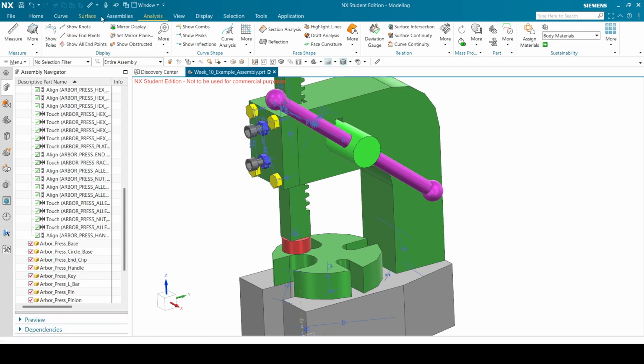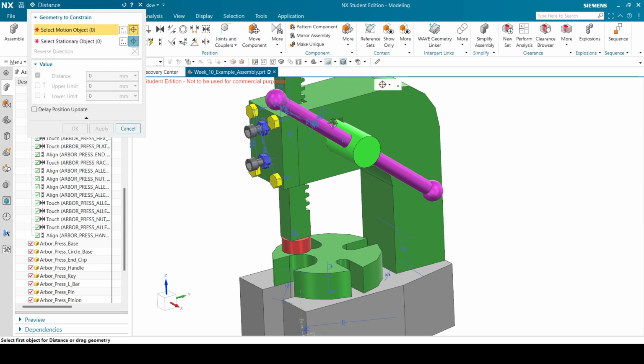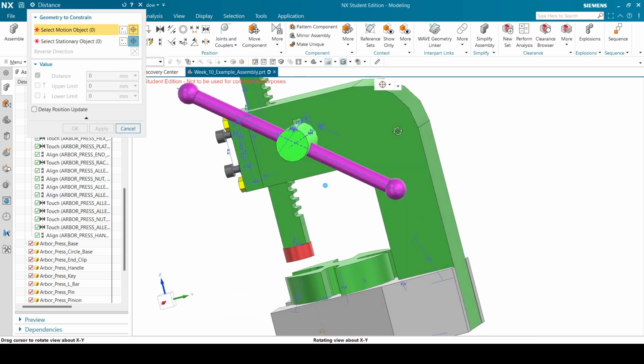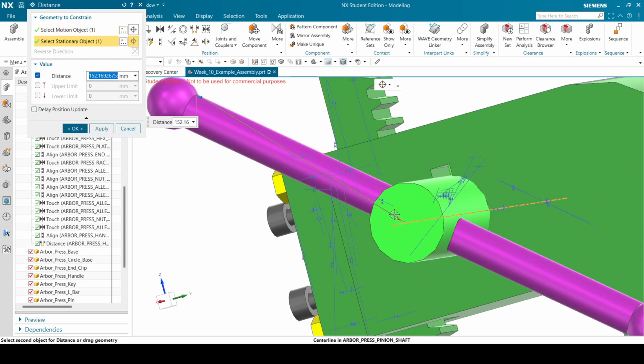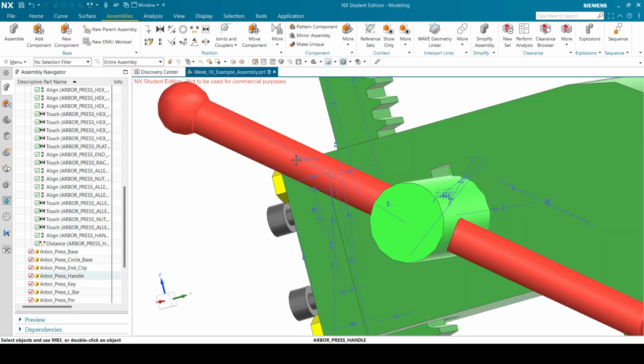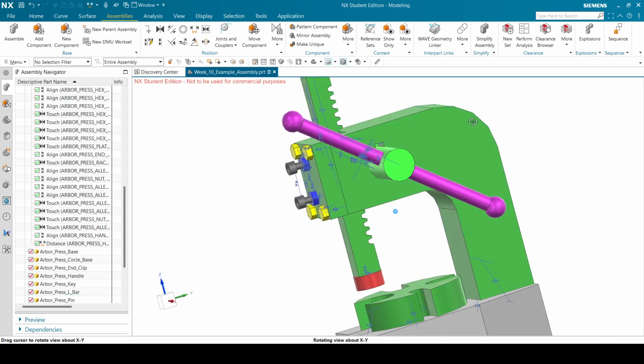Okay. So now I can just add a distance constraint over here and say, okay, this edge and this center line should be based. So Control V, the 290, the 2 is just cut off. So let's just go this way, 290, point all these zeros. I'm just going to get rid of them, divided by 2, because half of it. Enter, you see it did the math, and now it is beautifully centered.